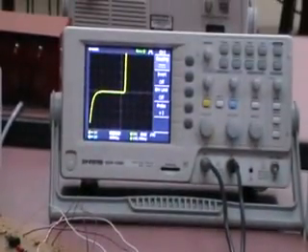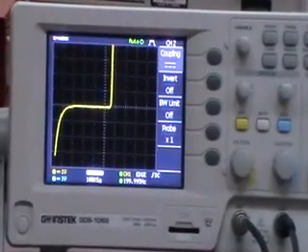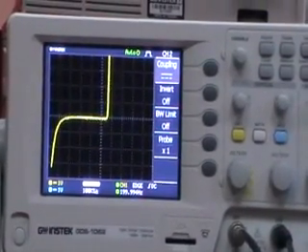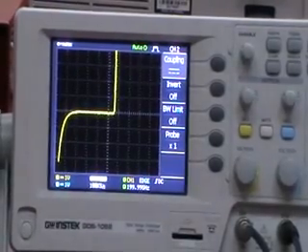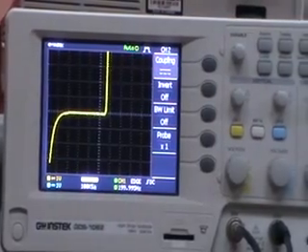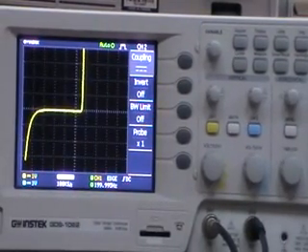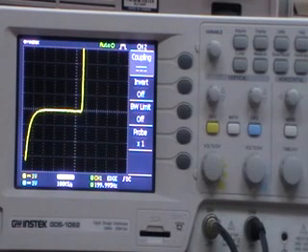The Zener diode in the forward bias case, or in the first quadrant, will act similarly to a general diode. In the reverse bias case, it will have a breakdown voltage where the reverse saturation current suddenly increases. So repeat all the steps that we have done previously, and the last step, along with finding the knee voltage, is to find the Zener breakdown voltage.